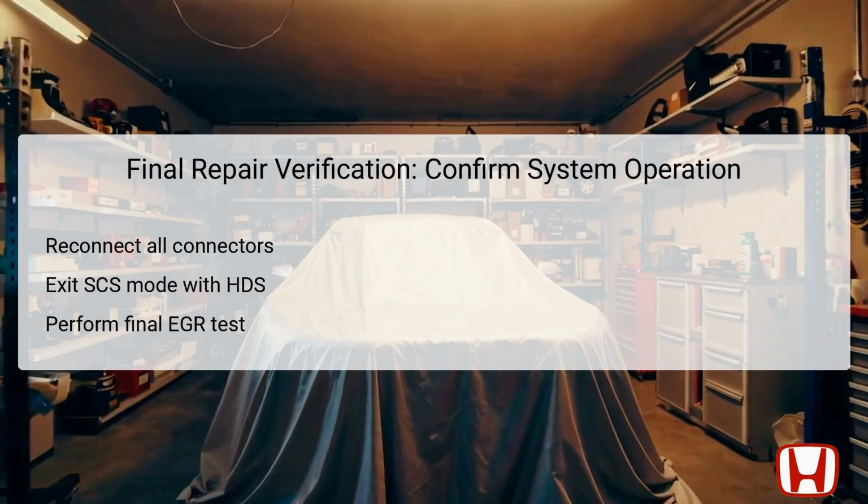After completing all repairs or component replacements, perform a final verification to confirm the system functions correctly. Reconnect all electrical connectors, ensure no wiring damage remains, and exit the SCS mode using the Honda HDS scan tool. Then, reset the PCM, perform the idle learn procedure, and execute the EGR test again.